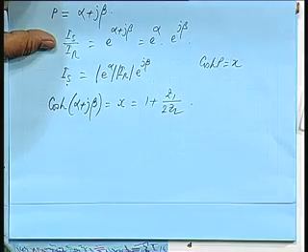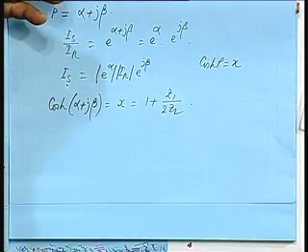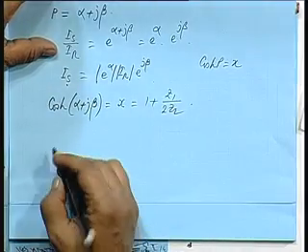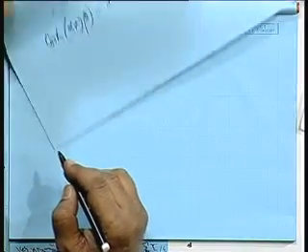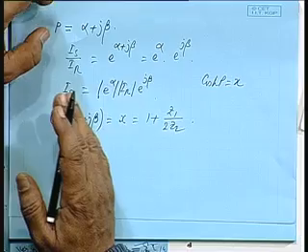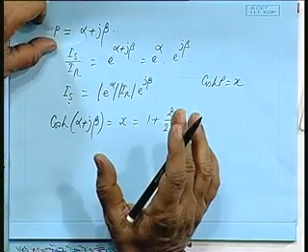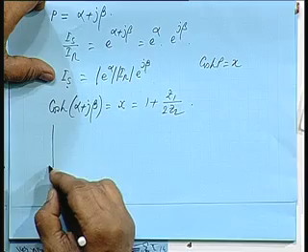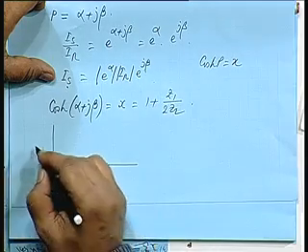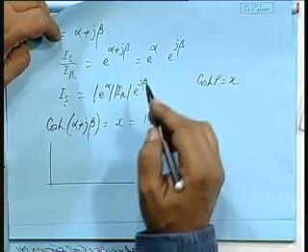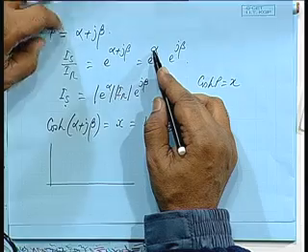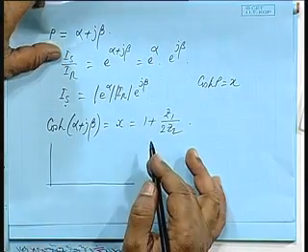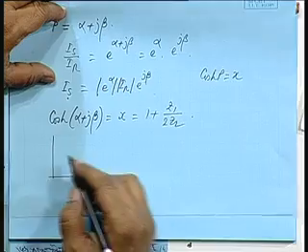Now, from the discussion on what exactly the filter is supposed to do, we have seen the filter is basically supposed to allow a certain band of frequency unattenuated. So, for the low pass filter, if I consider alpha, when alpha is 0, this is 1, that means the ratio of the current is 1, current is not suffering any change in magnitude.